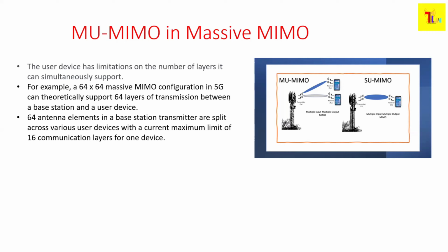Yes, whatever you said is correct. Whatever single-user MIMO can deliver, the throughput is only on a per-user basis. Your overall system will be defined only from the single-user perspective. Only a particular user can get more data or less data. In the single-user case, multiple antennas are used to serve only one user. Here on the gNodeB side, even though you are using 4 antennas, it will be delivering only to one user.